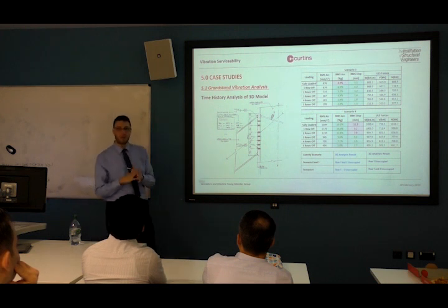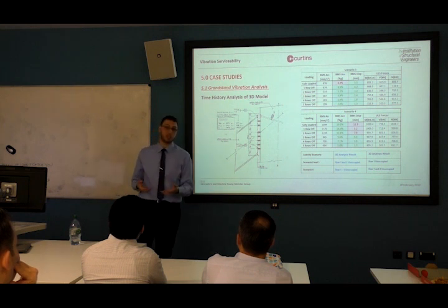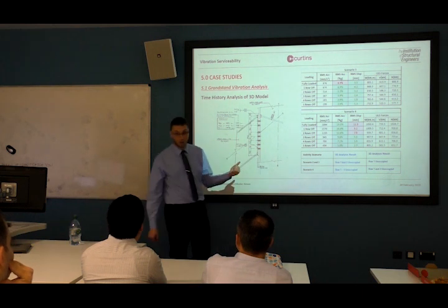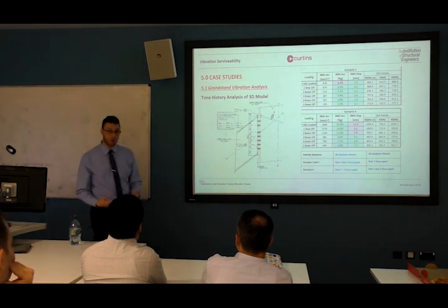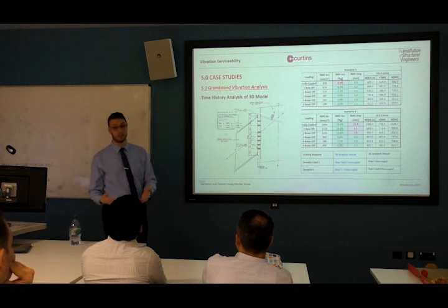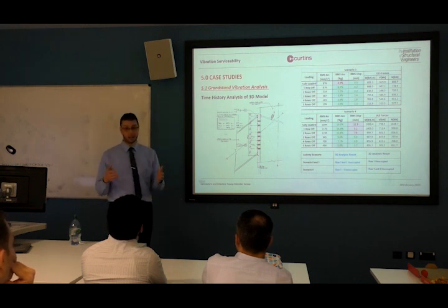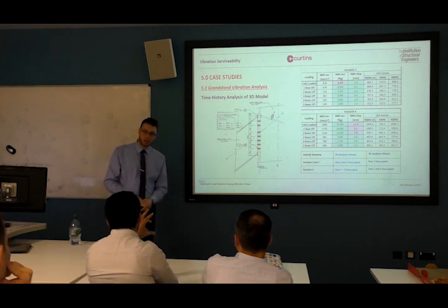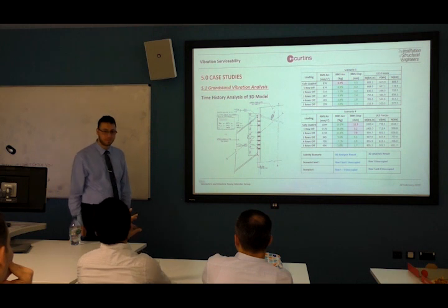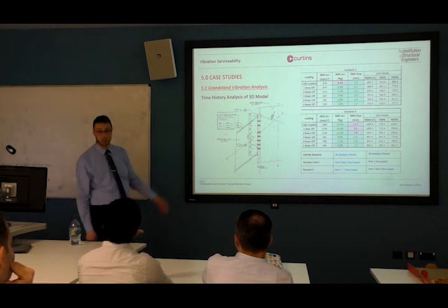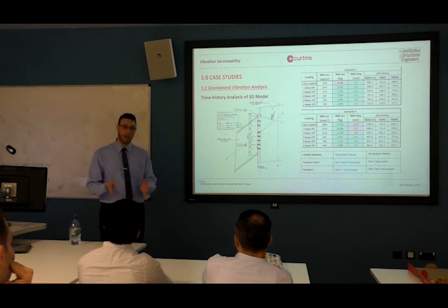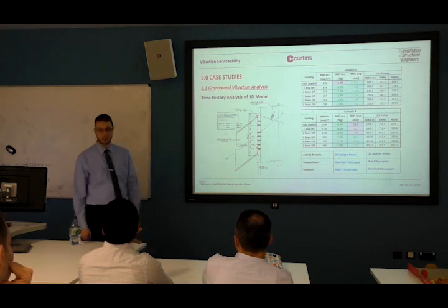Okay. So if the load itself is very small, you take it as rigid. Example is walking. But in this case, the load is not small at all. The load is massive, and you need to actually represent it as it is. So the IStructE, as a guidance, pinned connection, it's not... So, in your model, have you changed it from pinned connection to semi-rigid? It's a semi-rigid connection, in your model and in reality. So you didn't change? No.